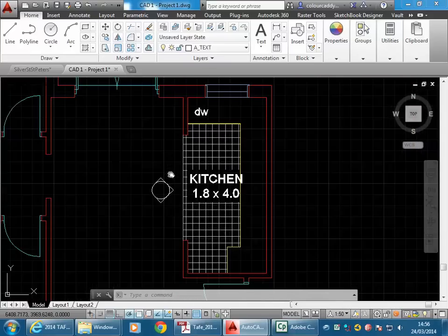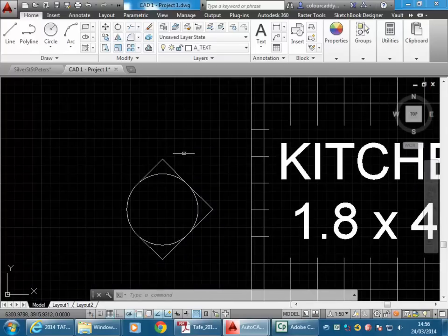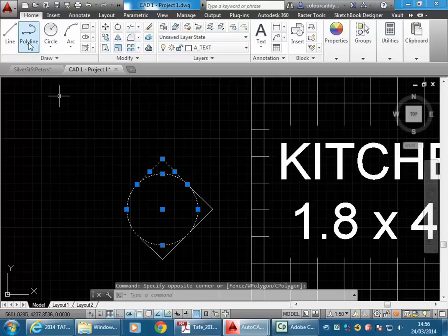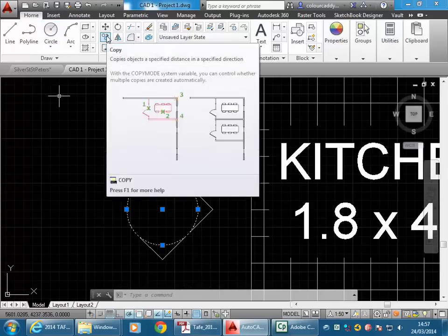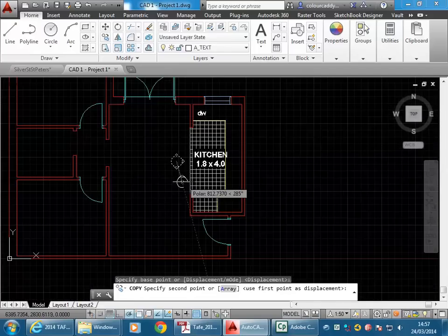And so you've probably seen similar symbols, at least for section lines. You would have seen the section symbol, and so I'm going to do one of those as well, just by copying this part of it, and then with the copy button, I'll click a base point, pick it up, and then I'll place that just to one side of the plan.